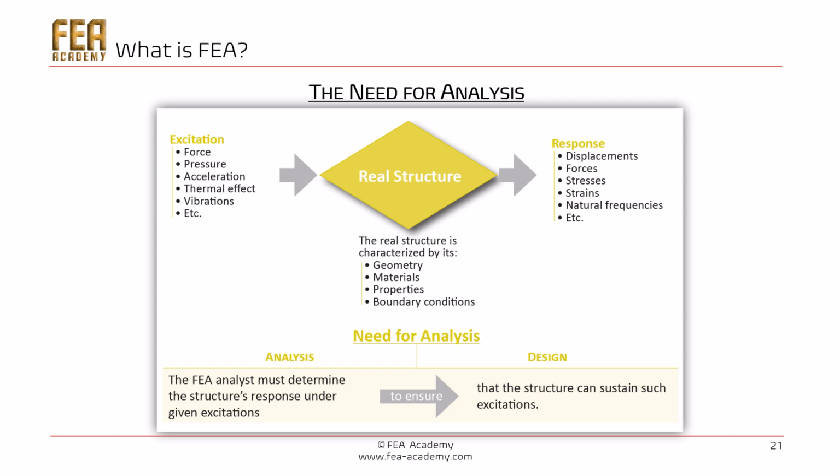By excitations, I mean forces, pressure, acceleration, thermal effects, vibrations, etc. And from that, what we want are the displacements, the forces, the stresses, the strains, the natural frequency, etc., resulting on the real structure. So the need for analysis comes from the fact that the FEA analyst must define the structure's response under given excitations in order to ensure that the structure can sustain the excitations.